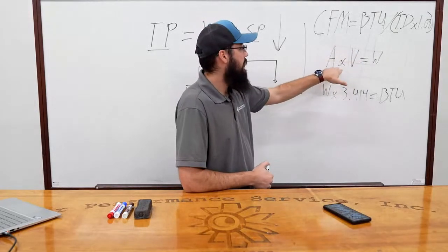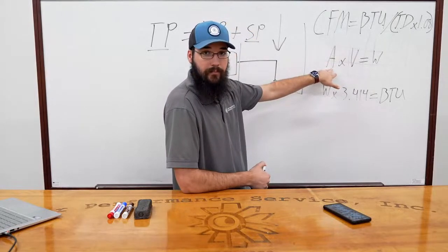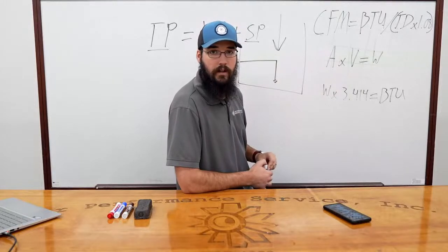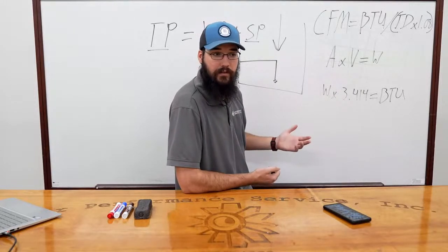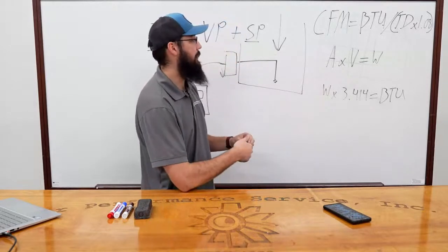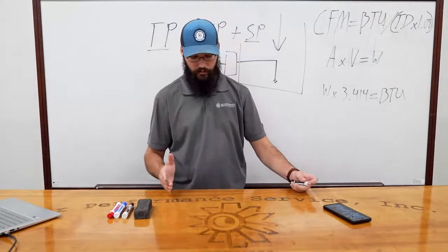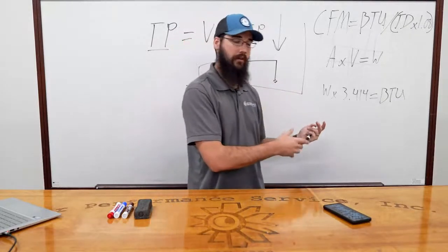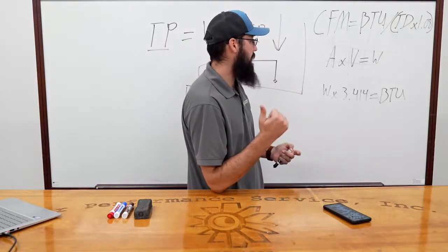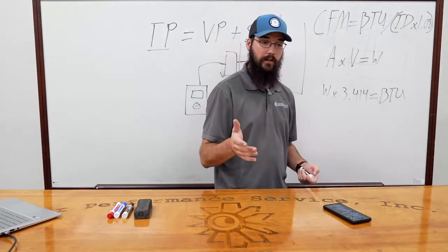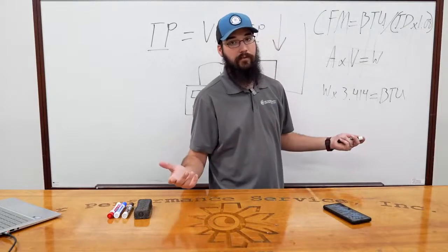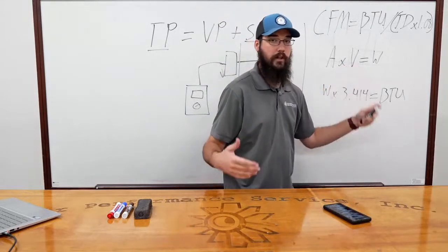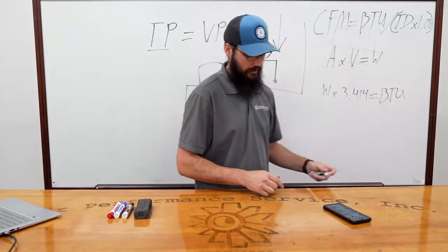Because you'll notice that you'll turn on all those electric heaters, and then all of a sudden your voltage will drop by several volts. That's pretty common to have happen. So the point is you're going this deep because you need accuracy. This is going to be what makes you the most accurate. In some cases, we have units that are rated for 460 on the data tag, but we're actually feeding it 480, 490. That's going to affect this reading if you try to use the data tag voltage as your calculation.